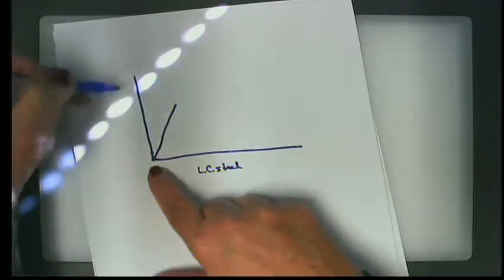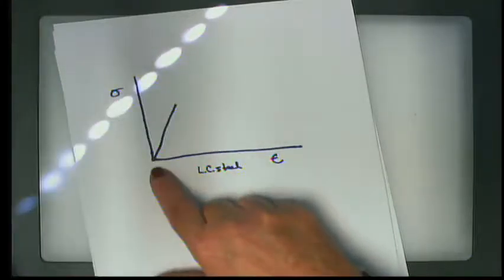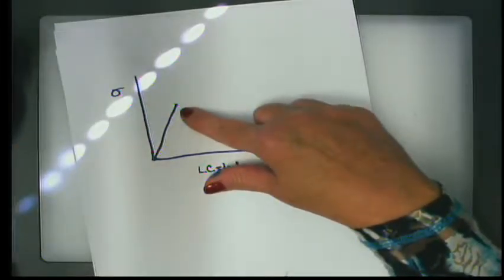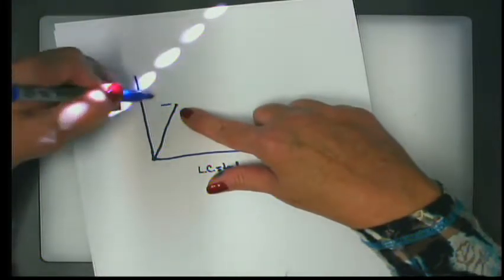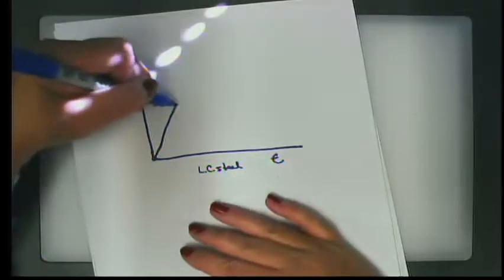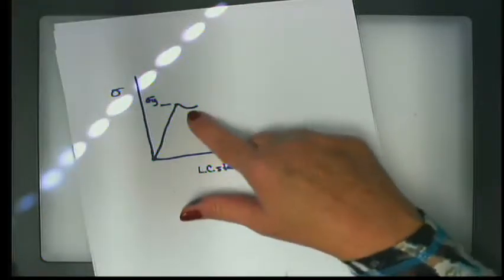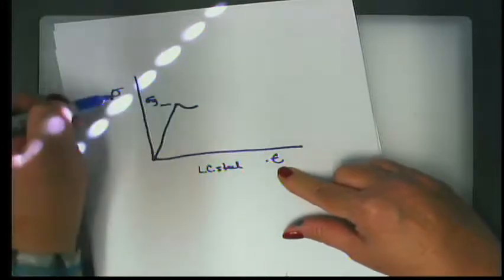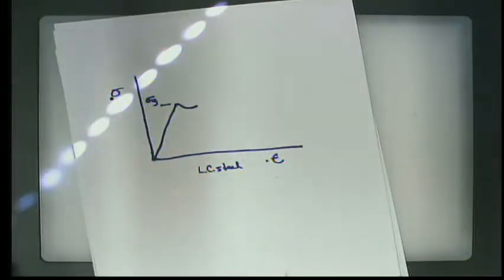But we start at 0, 0, where we have sigma versus epsilon, and we stay within the elastic limit to some particular value of sigma, which once again we refer to as sigma yield, or sigma sub y. And then the material actually yields. And what happens is you see a dip in sigma for epsilon. So since this is the change in length, and this is the change in stress, what we're really talking about is you pull on something with a particular force, right? And then you pull on it with less force and it continues to elongate.